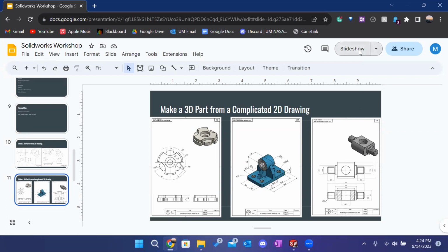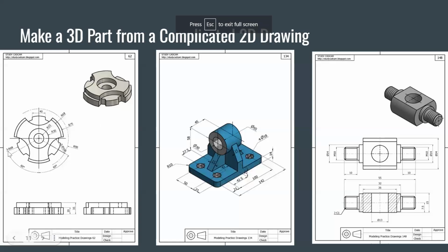So I can show this. Very helpful. So you can see this 3-R. That means that it's a pattern, and there's 3 radiuses of 60 inches. So this part would be 60 inches, this part would be 60 inches, and that part would be 60 inches. So whenever you see a 3 times or a 3 dash, it means that it's being repeated. So every 3 dash, diameter 18. So every single one of these holes, or 4 dash, every single one of these holes is going to be 18 inches in diameter, or millimeters, whatever it might be.